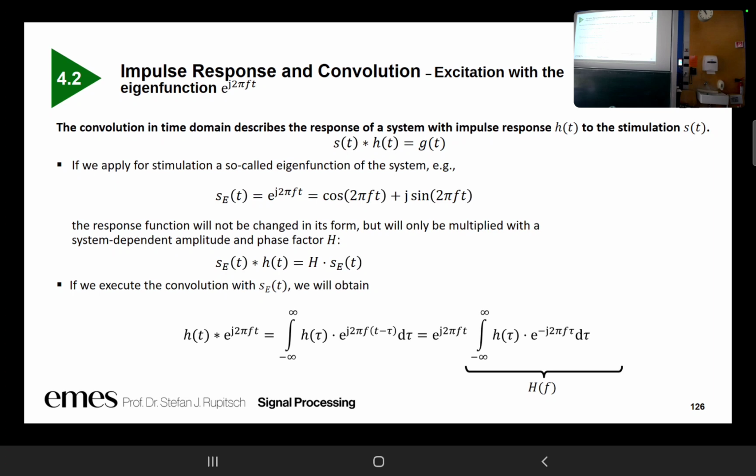You can transform the frequency response from the frequency domain into the time domain, and then you have the impulse response. You can use this to calculate the impulse response if you are not able to measure it. So you basically treat the system like a bunch of different frequencies, and from the frequency response you can transform back to the time domain.